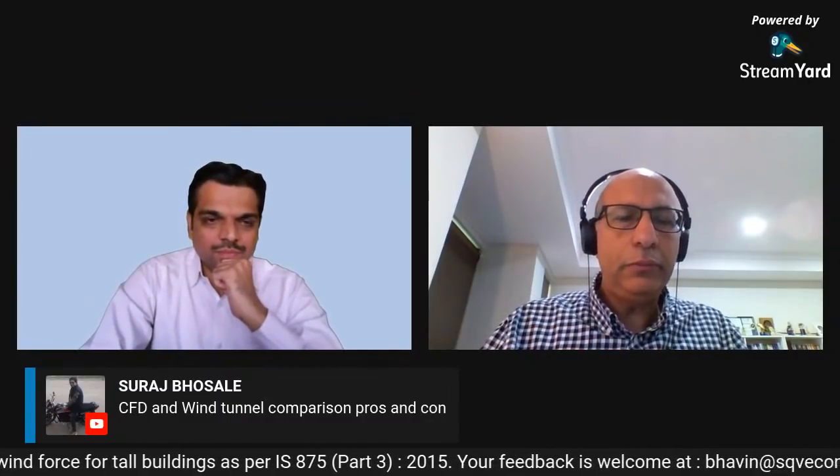But I would not use CFD alone for determining response of a tall building. Why? For a number of reasons. Computational fluid dynamics models, all different turbulence models, generally assume an isotropic environment, meaning the turbulence is the same in the horizontal, the crosswind, and in the vertical, which we know is completely not the case.